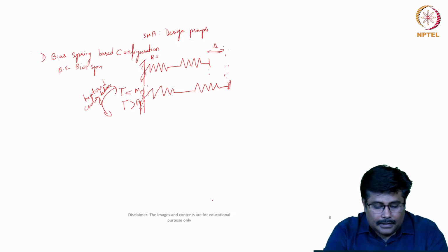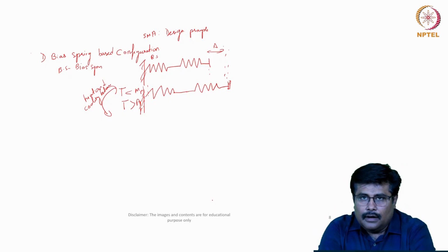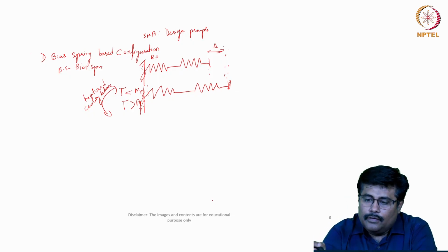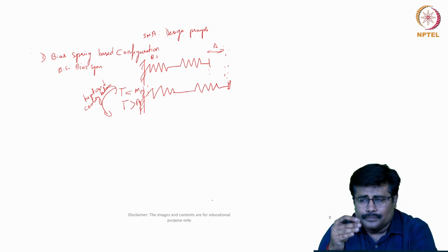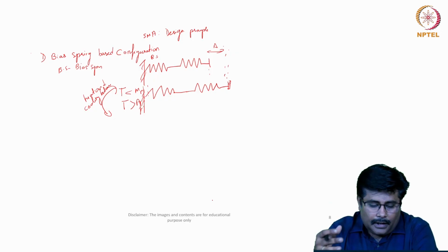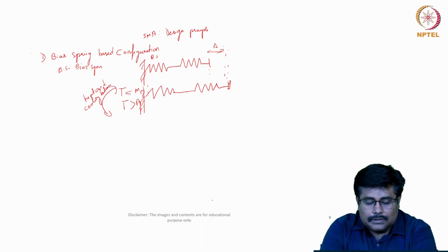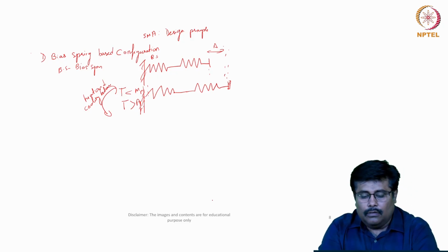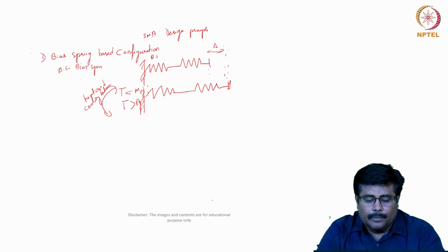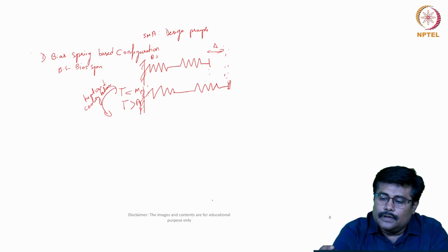There are different methods available to find this. One method, in fact, we had also demonstrated, is a Michelson interferometer. Using a Michelson interferometer, we can calibrate the spring, so we can study the overall fatigue life behavior of the spring. Some of the key aspects when we observe using this configuration: the maximum stress the system will experience upon shape recovery depends on the amount of preloading and the stiffness of the bias spring and the SMA used. Similarly, one more aspect is the stress versus temperature rate,